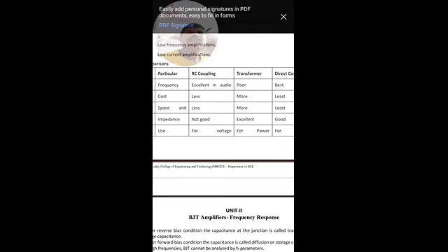RL dash, the output resistance, is made equal to the load RL by adjusting the turns ratio N. RL dash is equal to (N1 by N2) whole square into RL. So that is excellent in the transformer coupled amplifier. It is somewhat good in the direct coupled amplifier for impedance matching.